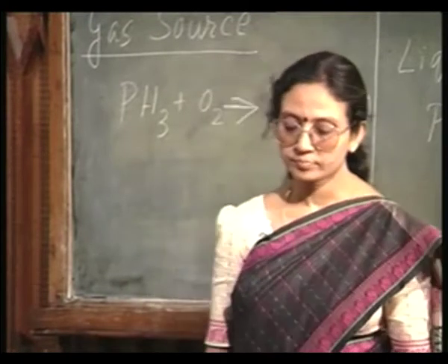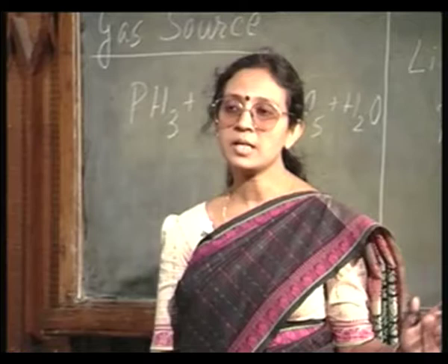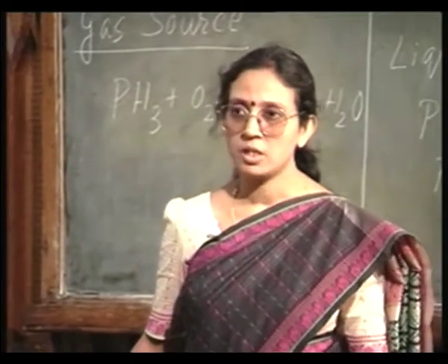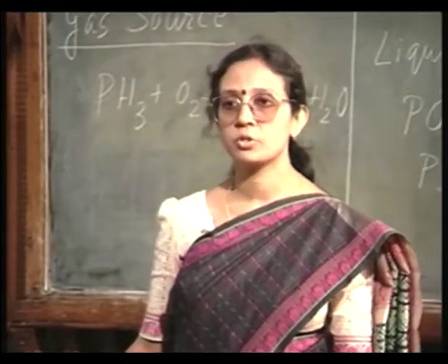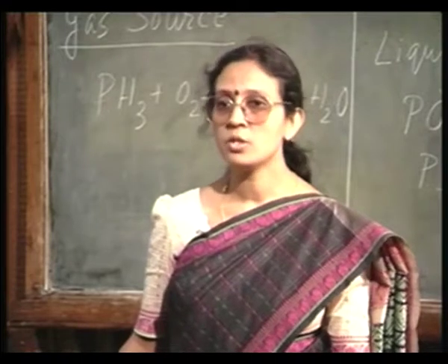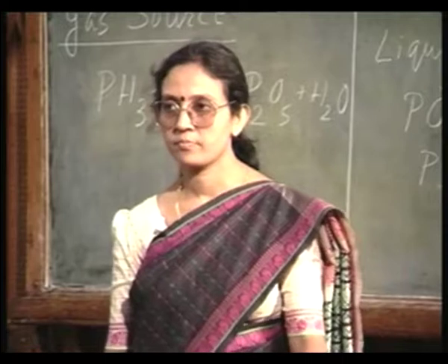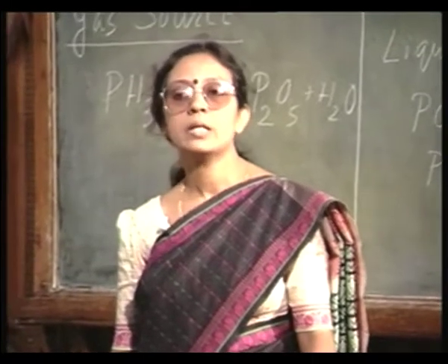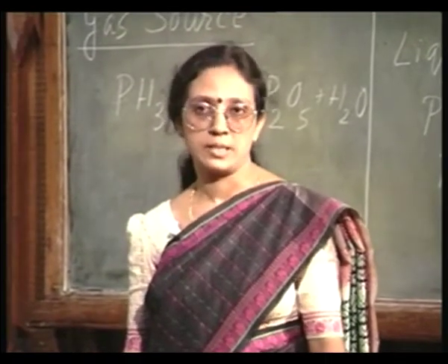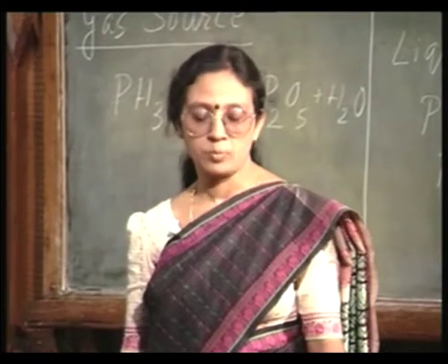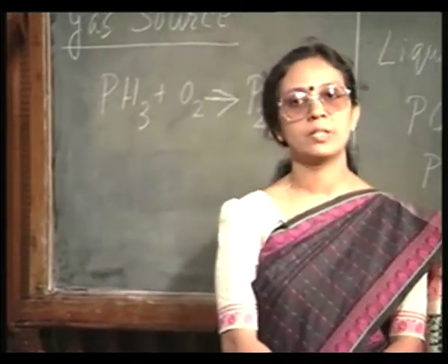And again essentially it is the same reaction, arsenic trioxide As2O3 reacting with silicon to release arsenic and form silicon dioxide. But when you are using arsenic as the N-type dopant, there are some factors you must be very careful about.